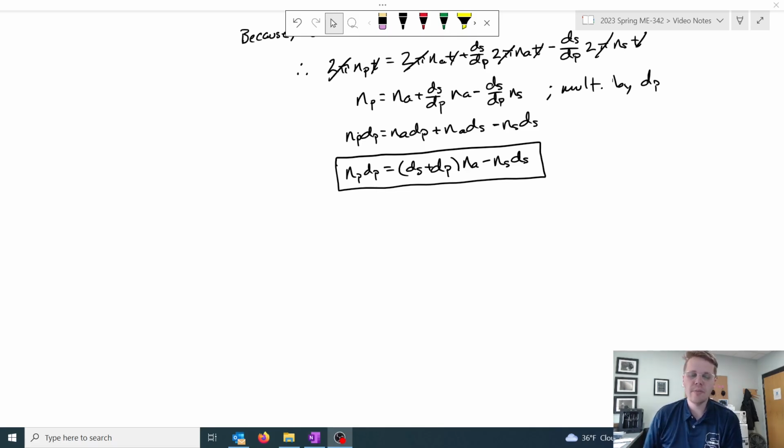In addition, because the diameters are related to the number of teeth on the gear, which is oftentimes what I might know if I purchase a gear, I could rewrite this whole thing in terms of the number of teeth on the gear rather than diameters. And it would be the same. My units don't really matter because to solve for any of the speeds, I'm dividing diameter by diameter, so it's unitless in that way anyways. So whether I express it in terms of gear diameter or gear teeth doesn't really make any difference.